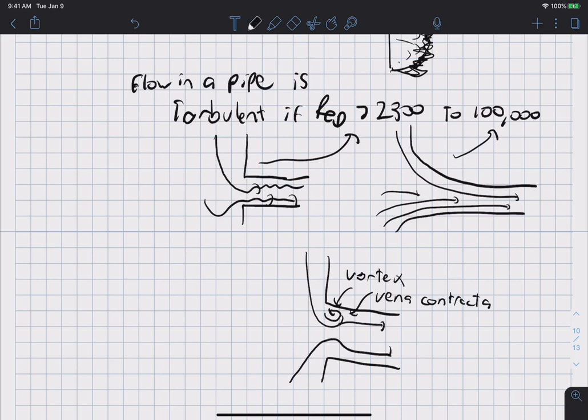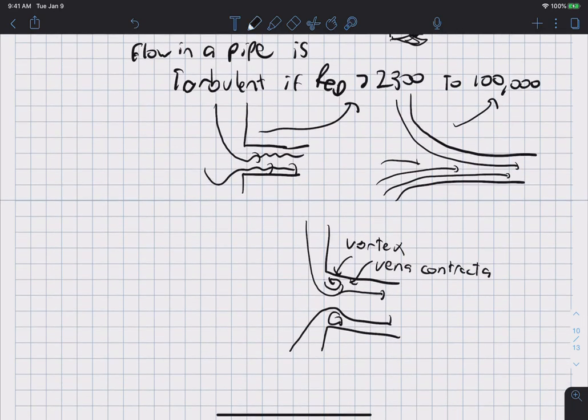And we'll discuss those a little bit more when we discuss minor losses, because it takes a lot of power to actually spin the fluid in this vena contracta, and so there's a significant pressure drop as the flow goes down and around this corner here, as opposed to if you smoothly contoured the inlet. And this so-called trips the boundary layer into turbulence.